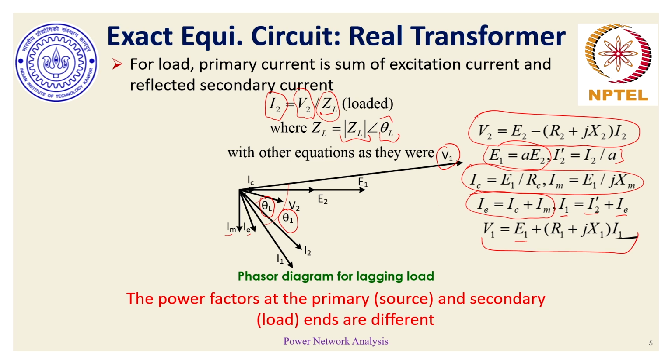So the phase angles change, and hence the power factors at the primary and secondary sides may be different even for the same load appearing on the secondary side. The reason for this difference comes in because of all the non-idealities that exist in a practical transformer. In an ideal transformer, phase angle differences won't exist as long as there are no losses and no excitation current.